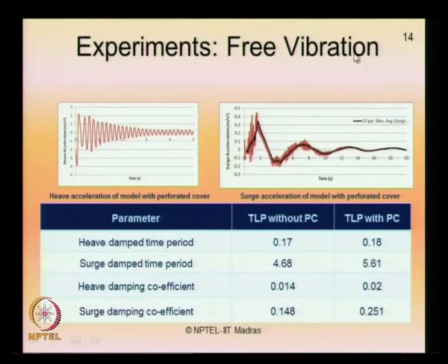Now free vibration tests have been conducted to understand the response characteristics in the heave and surge degrees of freedom. So if you look at the heave acceleration of the model with the perforated cover and the surge acceleration of the model with the perforated cover, as you see in the two figures on the left and right, the heave damped time period without perforated cover is around 0.17, whereas with perforated cover it is 0.18, that is on the heave, whereas in surge damped period you will see that there is a significant variation in the periods with and without perforated outer covers.